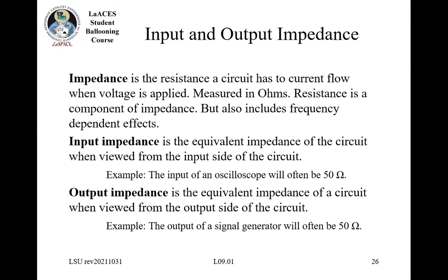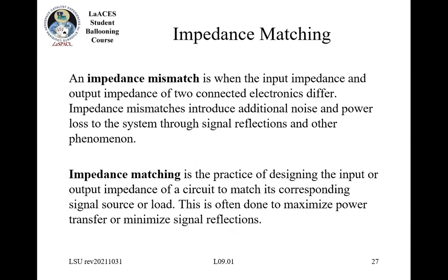Like I said, 50 ohms is going to be very common across a whole bunch of devices. Why we care about this is, as a rule of thumb, you want the output that is feeding into an input to match. That's called impedance matching. The reason you want that is a mismatch can cause additional noise.